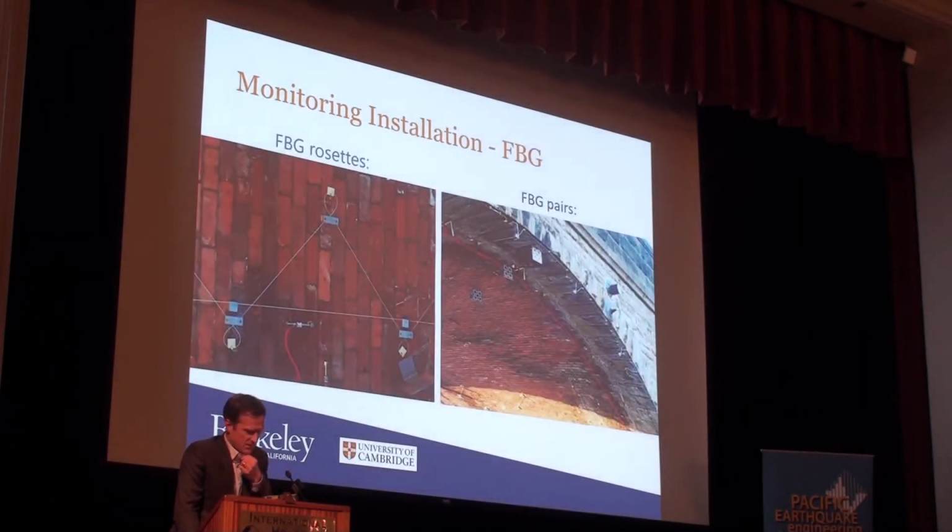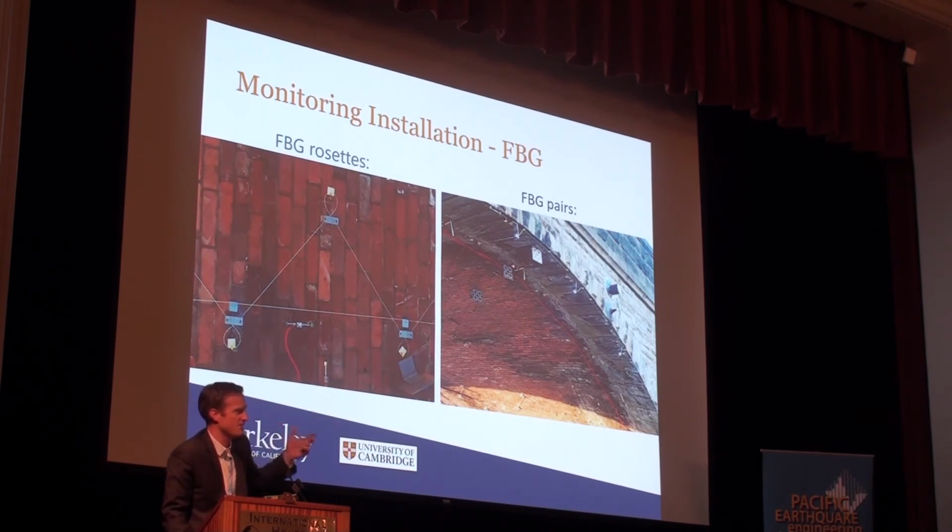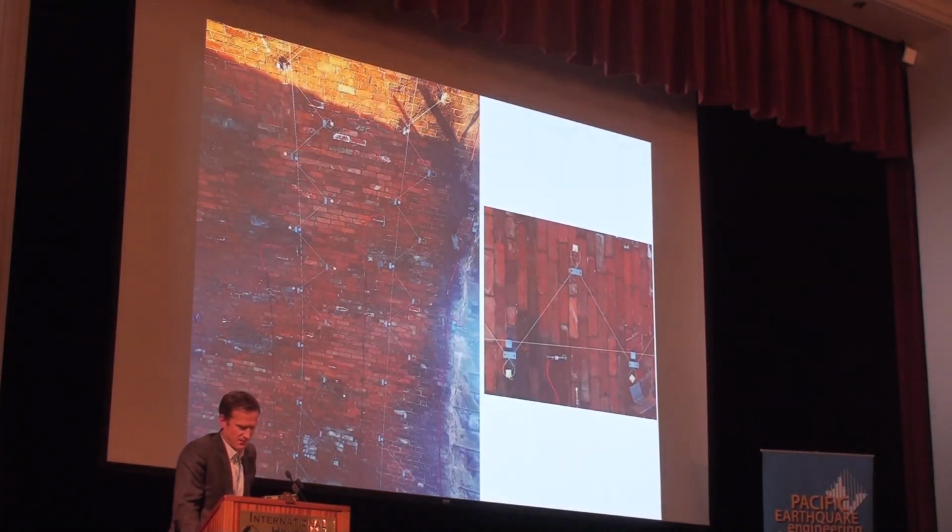I'll skip this here. So there you see the example installation. So we can string the fibers, curl them around, string them through. So you're clamping and stringing. That process is a bit intensive. The nice thing is then you leave the installation there and it's fairly durable. So this is meant to last. The other nice thing is that the fiber optic cable itself, again, is very durable. You can update the analyzer, which you connect to the end of the fiber, very easily by accessing the cabinet, changing out the analyzer. So in that sense, the long-term ability to measure things is quite unique and efficient.